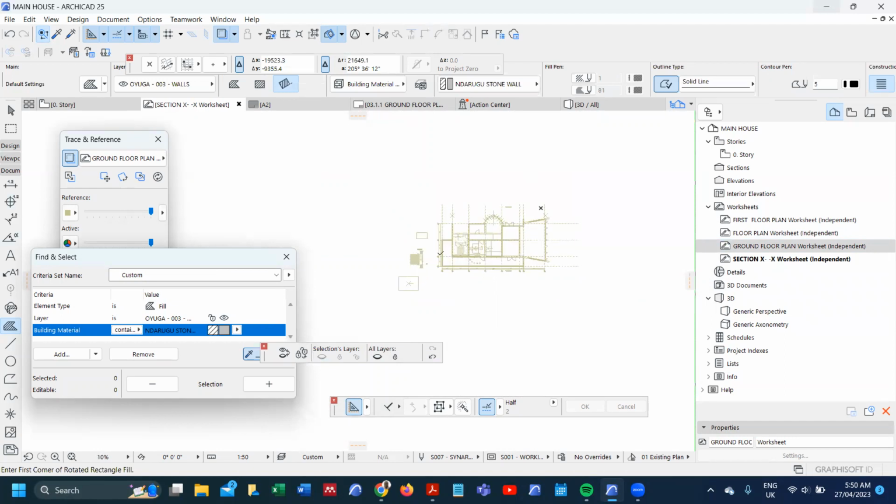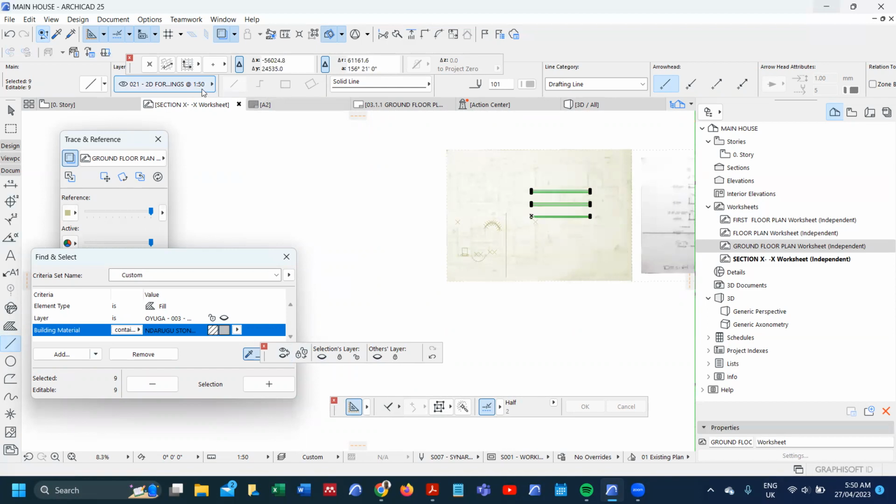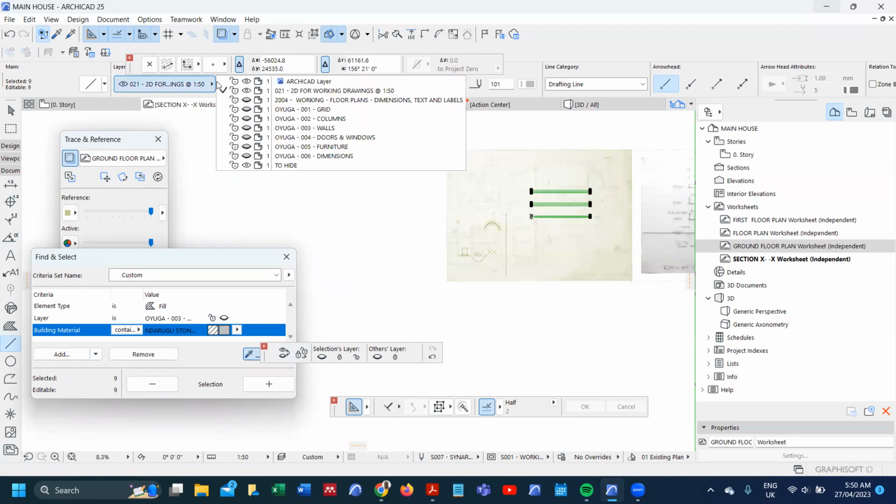There, okay? So I'll want now to rotate it. That tells me my lines, I've drawn certain lines and I say not to see them. So again, I place them in the wrong layer. So ensure that you always use the right layers.